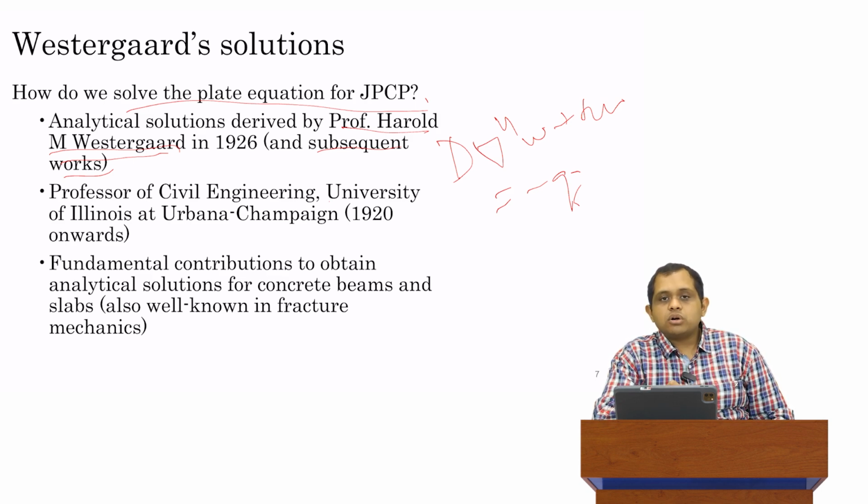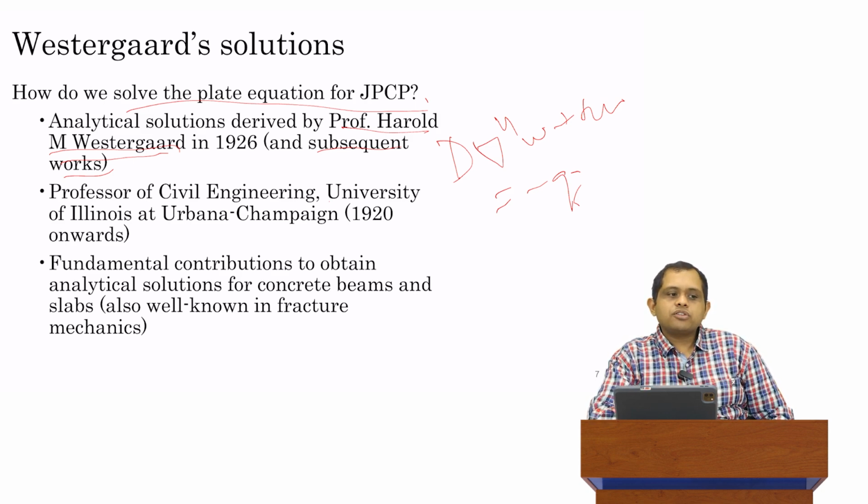But to this date, about 100 years after this paper was published in 1926, so 2026 will make it 100 years, it's not that far away, these Westergaard solutions are still the most celebrated set of analytical solutions for rigid pavements. It is still used very widely, and only recently in India and other countries have we moved away from these into more modern methods.